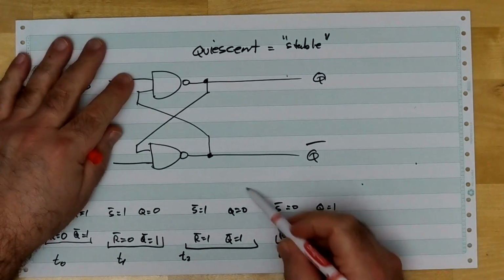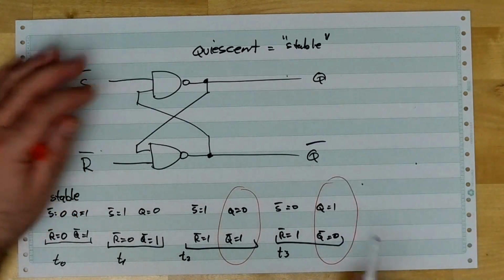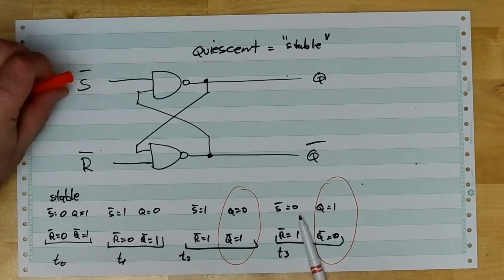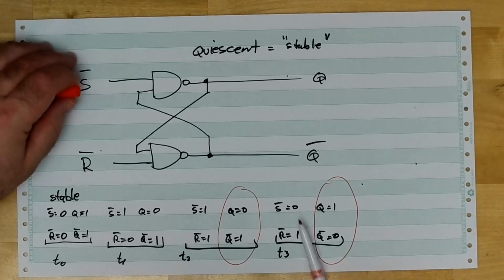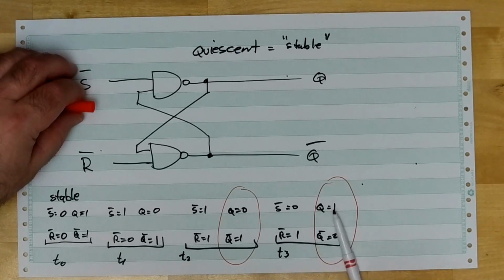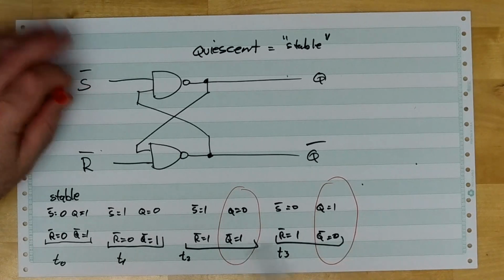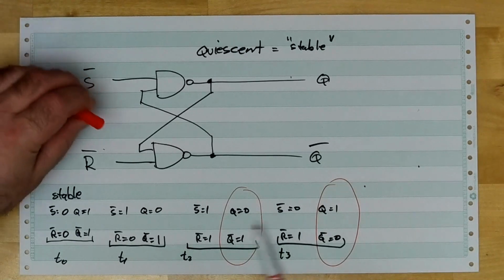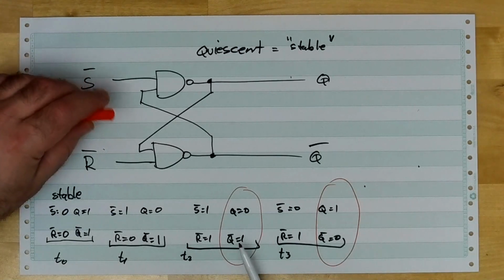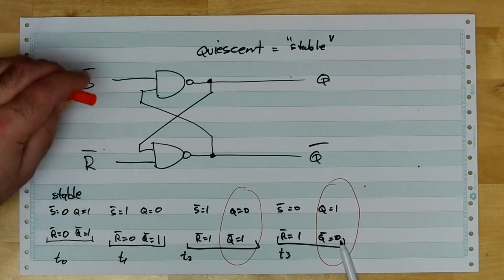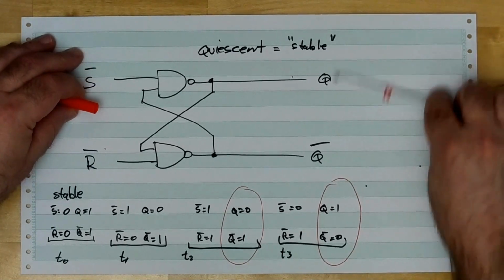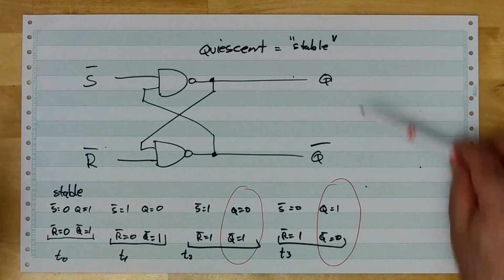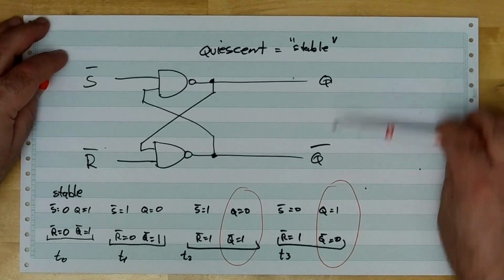Right? Look what is going on here. Both of these signals were 1s. I made one and only one of them a 0. And you can say that Q flipped to a 1, and at the same time, or thereabouts, and as a result of this same stimulus, Q changed from a 0 to a 1, and Q bar changed from a 1 to a 0. This is actually why we call these signals this way. All right, we name them such that under normal circumstances, these two signals will always be the opposite.